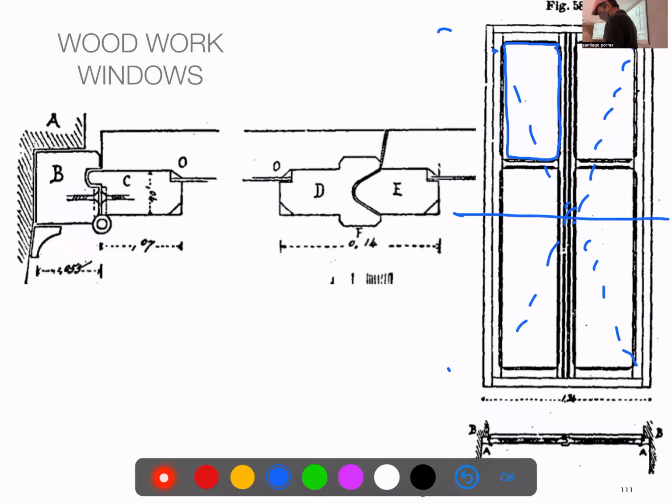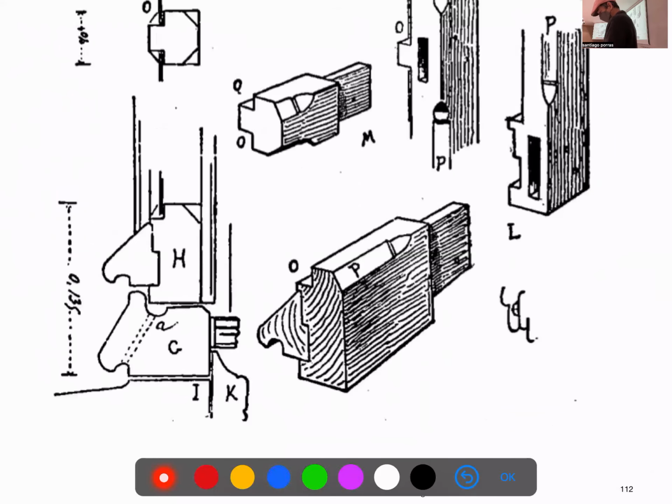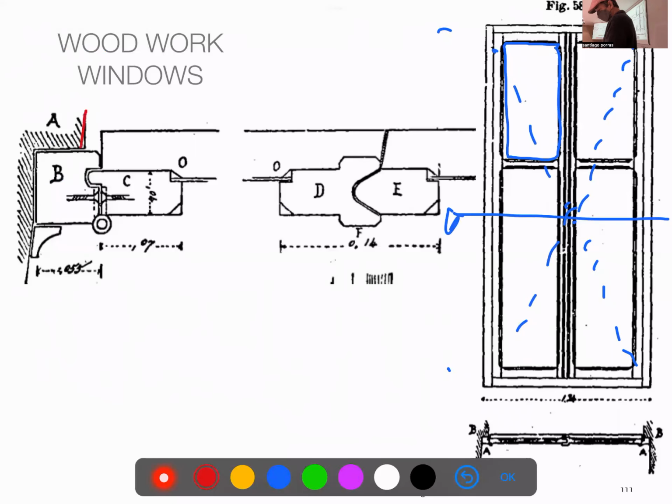So this is the horizontal section of the window. See things we already studied. The fabric always protecting as much as possible the frame of the window, right? They don't explain how it is done, but it will be fixed to the wall. See the trim just to cover those slits. Again, overlapping is traditional. There was no silicone back then.